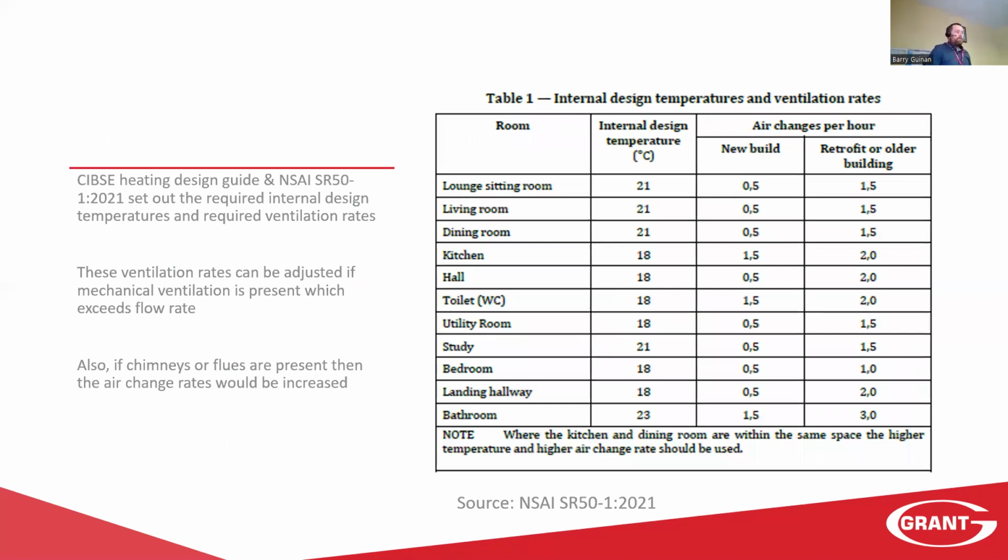The CIBSE Heating Design Guide and the standards we would use in Ireland, NSAI SR 50-1 and SR 50-4, which relate to plumbing and heating and heat pumps. So when we are designing heat loss calculations, there are a number of set criteria. These will be internal design temperatures for different rooms. Each room would have a specific target based on comfort levels, which are required to be reached.